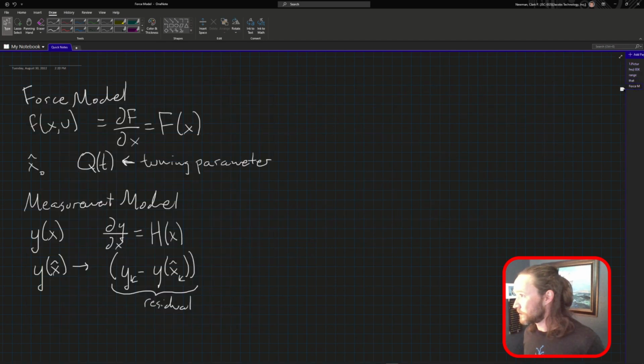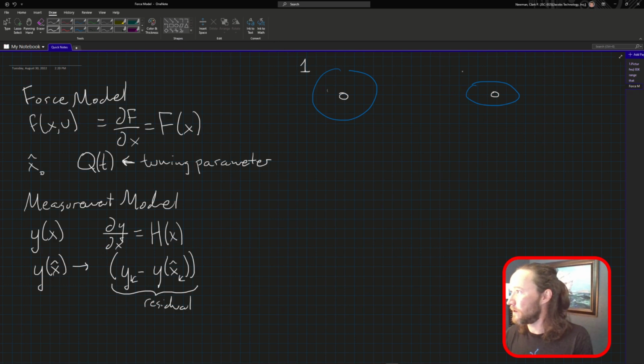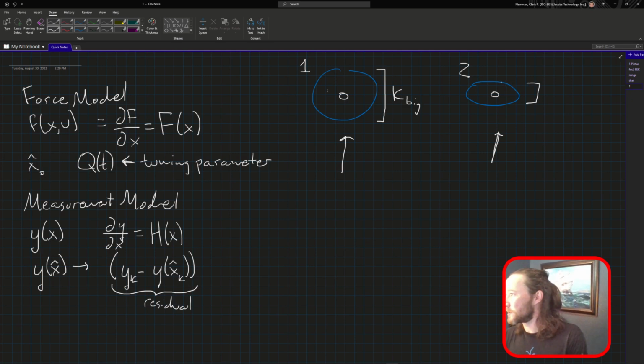Let's go back to here. So for example, going back to our little issue where we have covariance, we're going to look at two cases. We're taking a range measurement of this guy, this case, and this case. So taking a range measurement from this direction of spacecraft 1 will create a larger update due to the size of the covariance. So we're going to say K big. Now over here, the filter, by having less distance in this measurement direction, effectively has higher confidence in the position of the state in that direction. So it will not accept big updates.